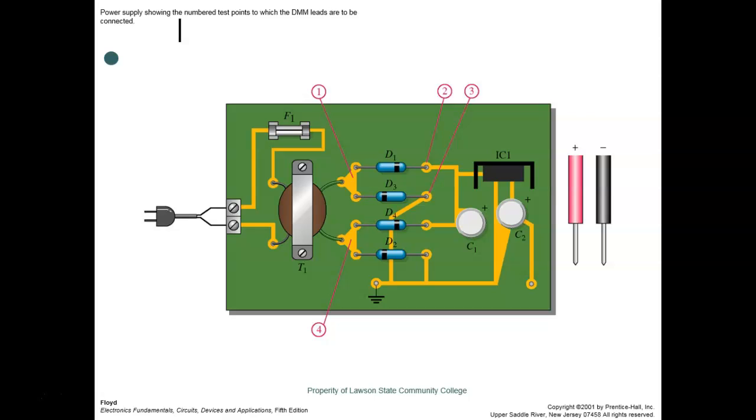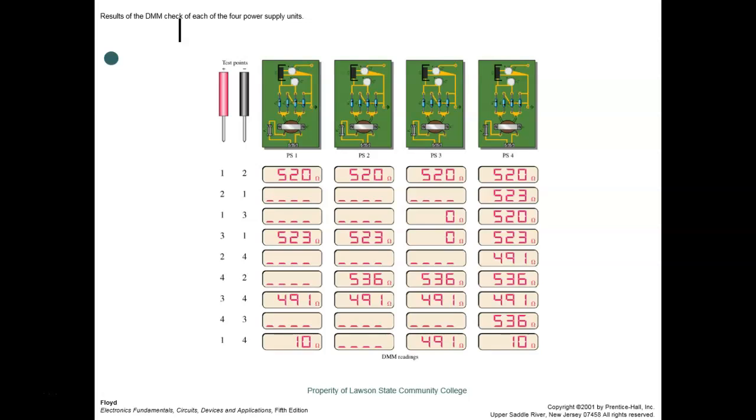And when we open up the trainer, it's going to have this same arrangement, but it's not going to have diodes. It's going to have one of these in there. And you can look at it, and it's got 2 leads labeled AC, and then it's got 2 leads labeled plus and minus. We did have one that burned up, and I replaced it with 4 diodes.